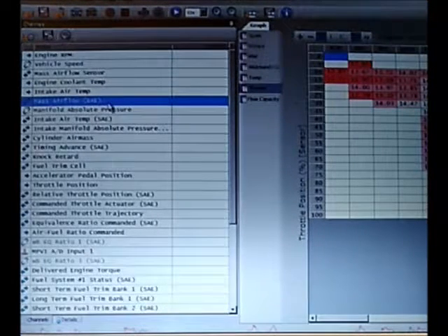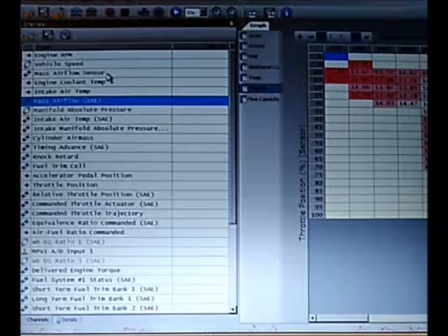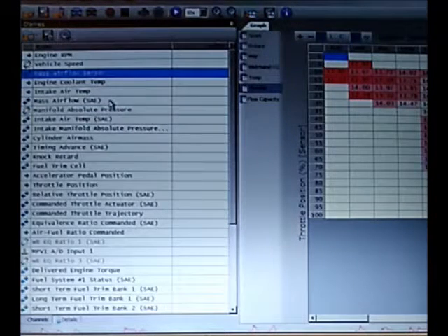Mass airflow SAE, so you don't need both. You don't need two mass airflow sensor PIDs. Pick the one that allows you to record the frequencies that the sensor is putting out. Sometimes mass airflow is represented in grams per second, like grams of air per second. So it's a different unit. You don't want that. You want the one with frequency. So whichever of these gives you frequency, just use the correct one.